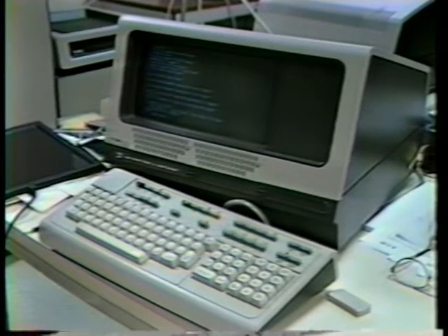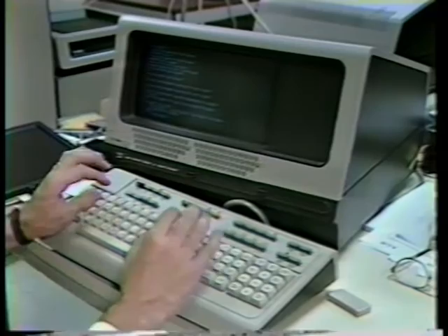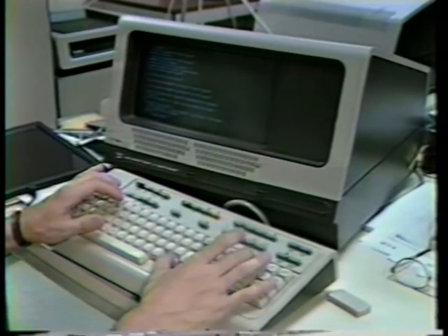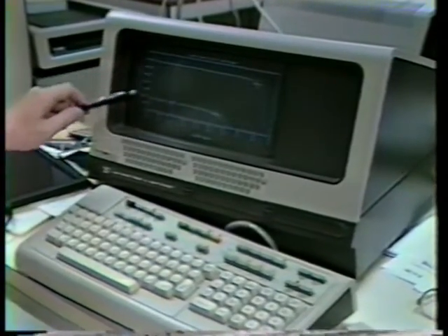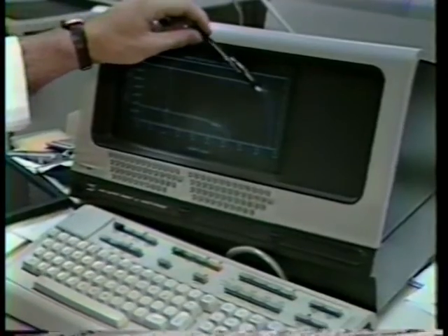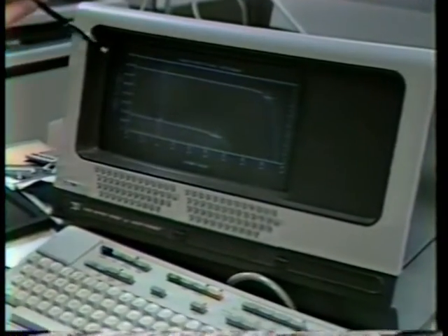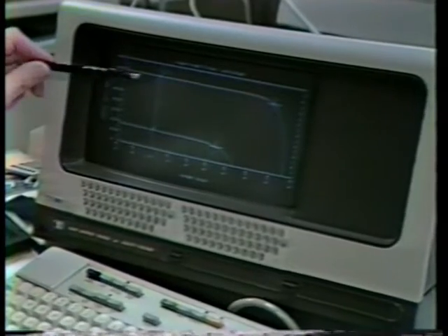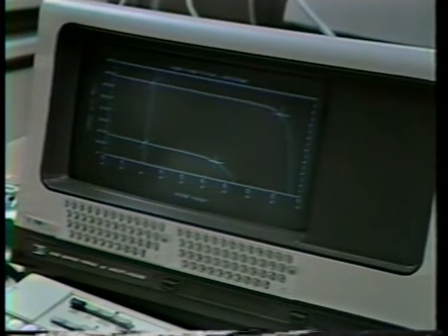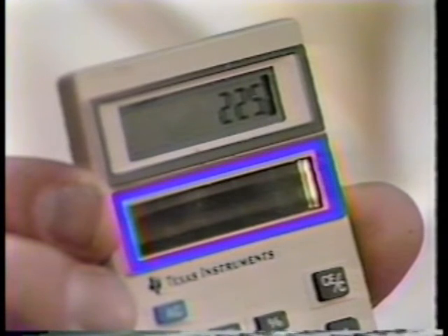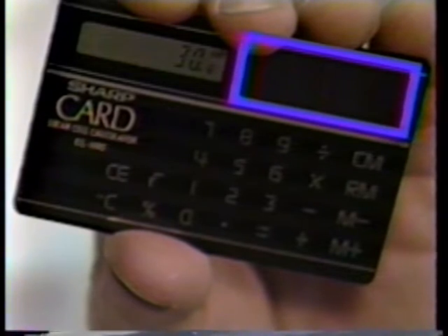The automated measurement system has now evaluated a solar cell, and I will plot the cell up. The curve here represents a good solar cell, while this curve represents a bad solar cell. The points marked here are the maximum power points. This axis is current, and this axis is voltage, and these points mark the short circuit current points. The future of solar cells is more efficiency at lower cost. Solar cells, or photovoltaic devices, are appearing in technology where electricity is needed in a small space, like calculators, which can use them instead of batteries.